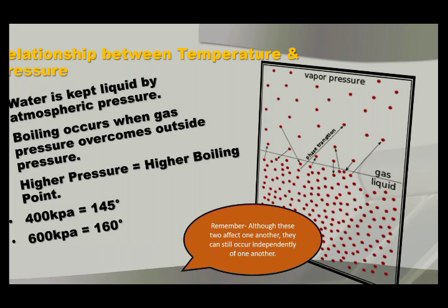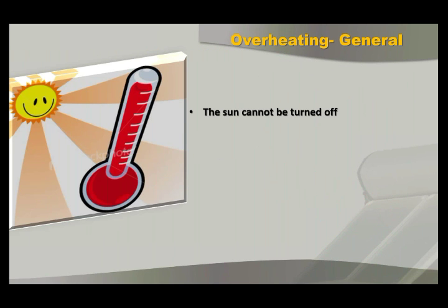We've all seen calcification and limescale buildup within valves. This sort of thing does happen. Just to give an indication and to illustrate it, for the guys up in Joburg, I think your water boiling point is about 92 degrees Celsius. Down here at sea level, it's 100 degrees Celsius. So there is a major difference in the temperature at which water boils when you're talking about pressure.